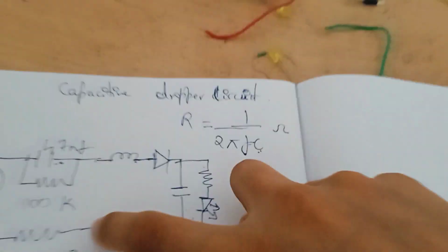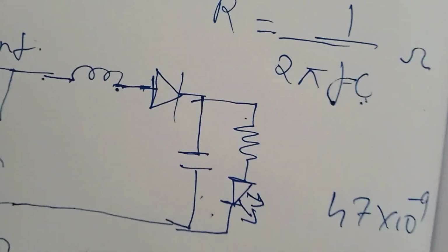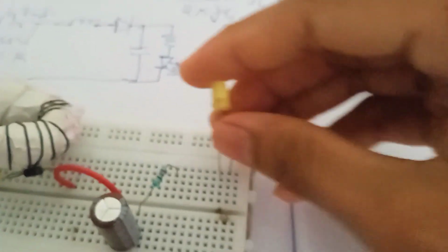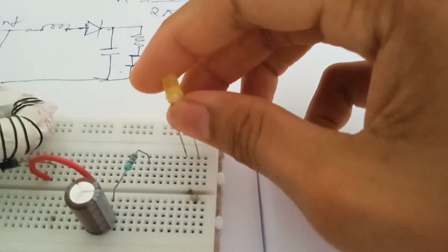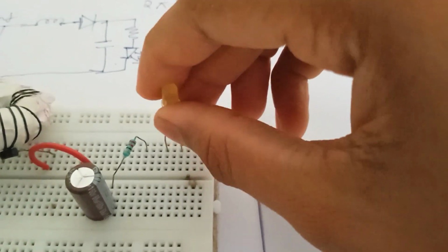Then comes the LED, and we have to do the rest of the things. Here is the 220 ohm resistor, and this much is done. So now I push it down. Half of the circuit is done. Now I have to connect this. Here comes this LED. Turn it over here, then add this large resistor.